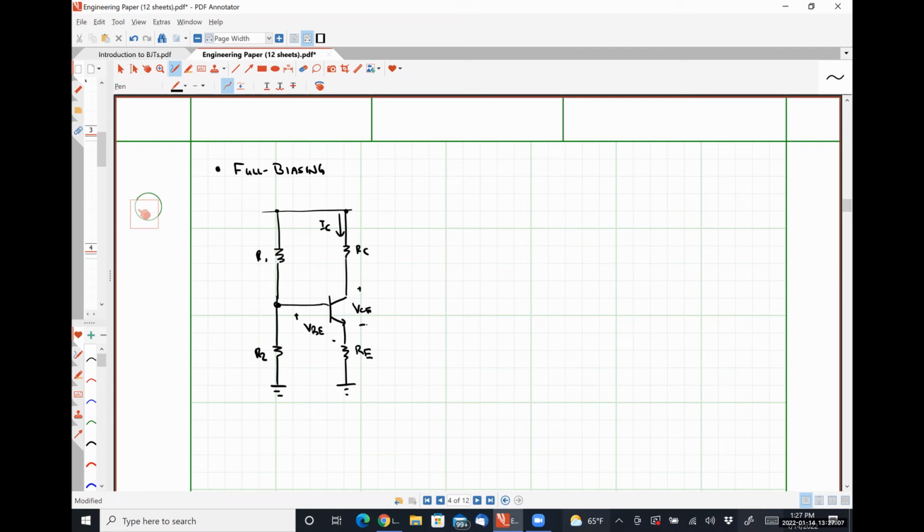So to analyze this guy, we're going to actually have to use our large signal model, but it should be fairly obvious that we can use the results of our previous analysis to simplify this guy by putting Vthevenin in series with Rthevenin on the input side of this guy, on the base side of this guy.